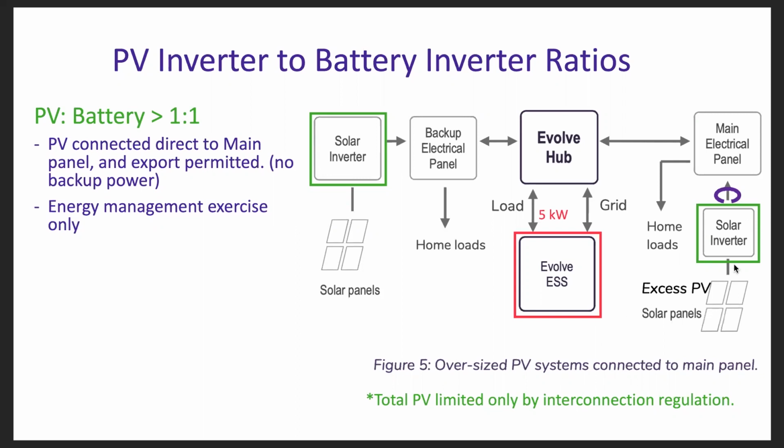That total PV system size will only be limited by the interconnection regulation, so from the utility, and that bus rating at the panel. Obviously you can do a line side tap, but we won't get into that here.